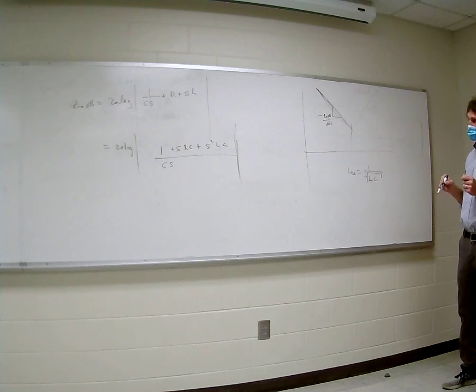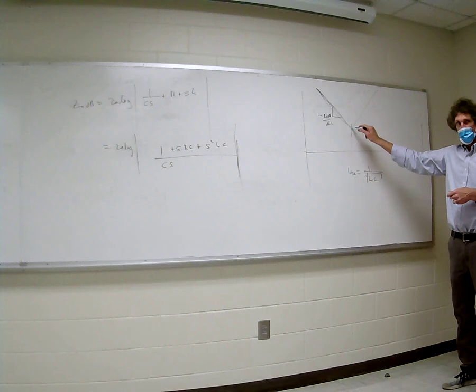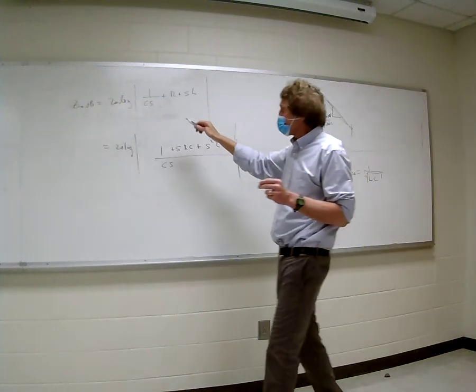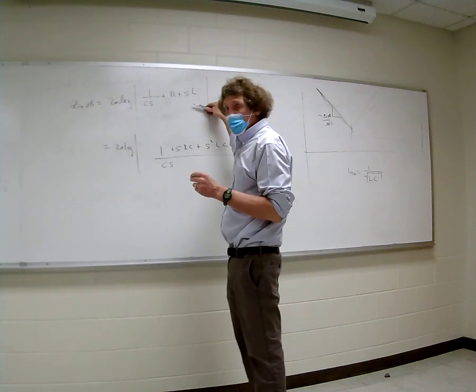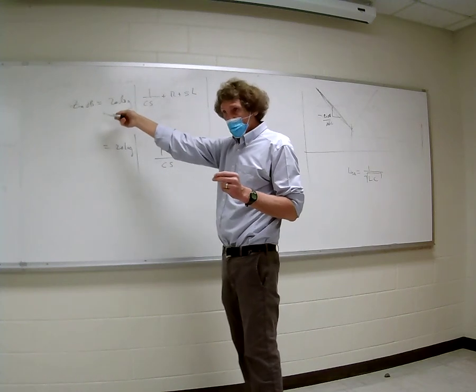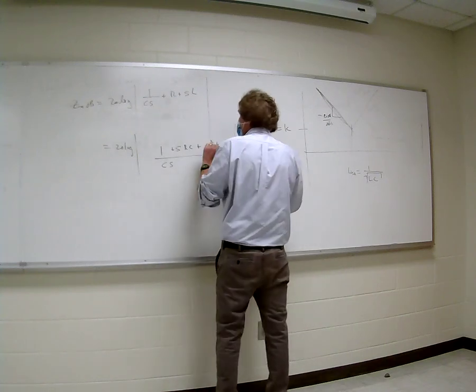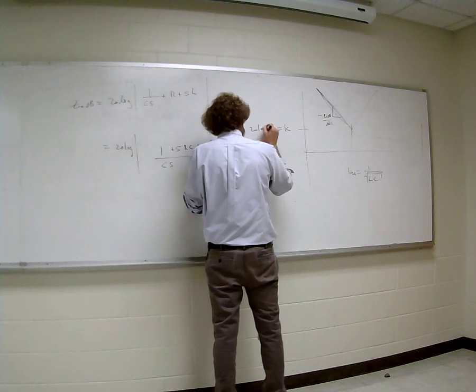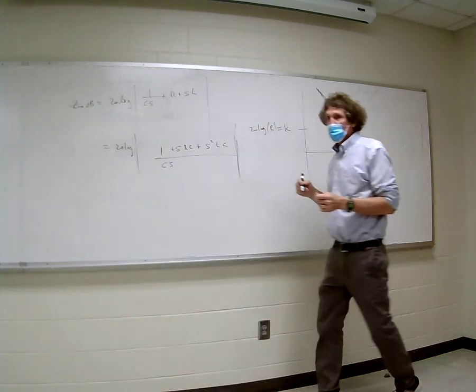So if we're going to get this thing, if we want values, I'm going to have to give you something, but first I'm going to show you how to get it. Well, this is the thing that's interesting right here. That's where the self-resonant frequency occurs. At that frequency, the capacitive impedance or reactance here will equal the inductive reactance here. And therefore, at self-resonance, 20 times the log of R will be the value here. So if this value right here is K, I can set it equal to 20 times the log of R. Y'all follow me on that?